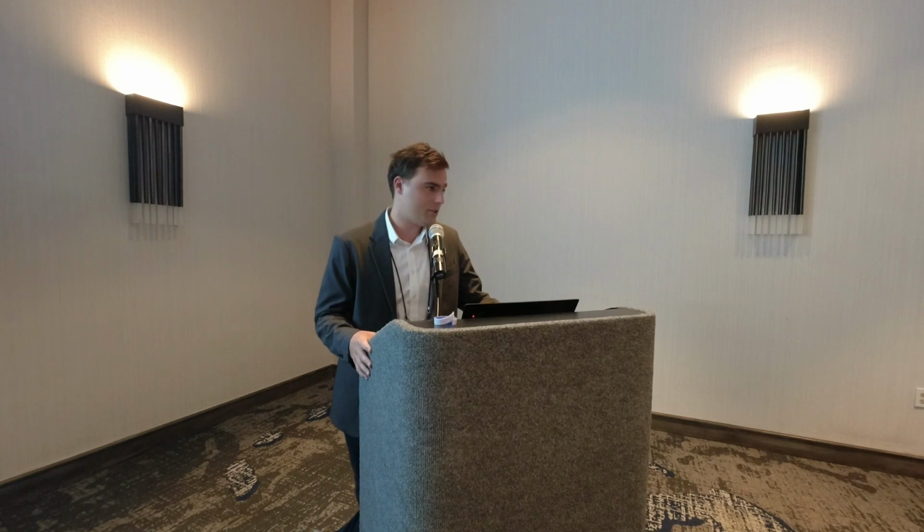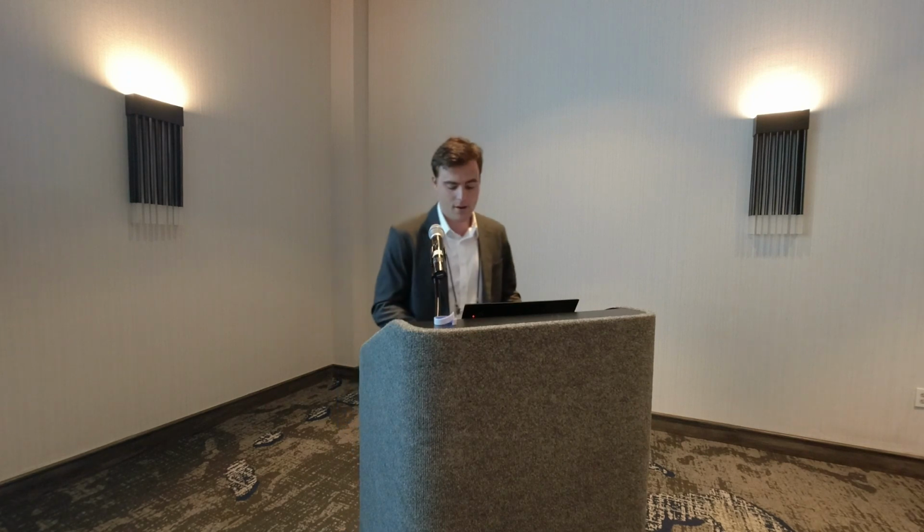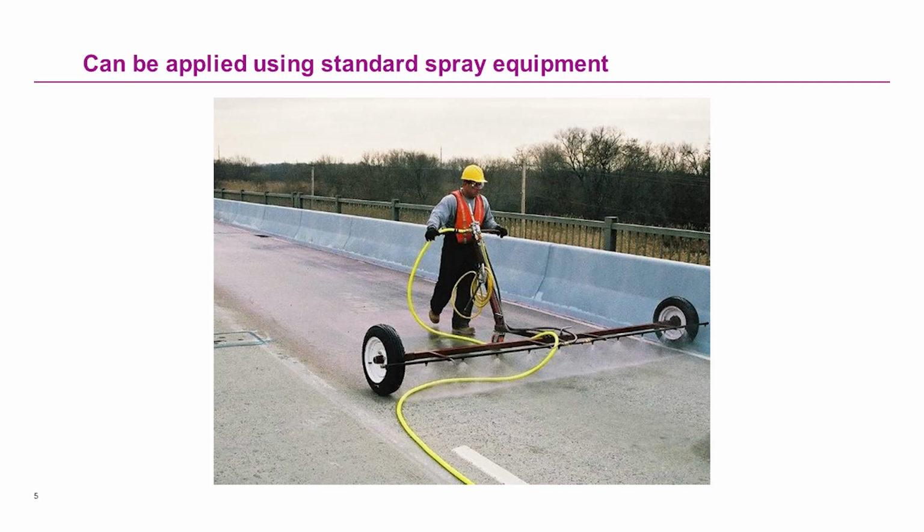We have testing that shows effectiveness upwards of 5,500 ppm of chloride at the rebar level, where the silane is still able to penetrate, interact, and repassivate the rebar. So here's just a little image to show easy application. This isn't really rocket science here.